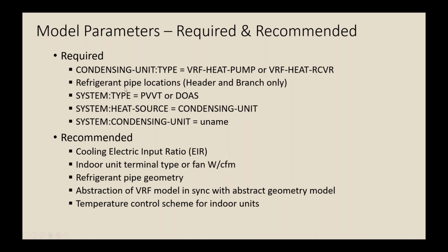You also have to specify the locations of refrigerant pipes, and I'll describe what these terms header and branch mean in terms of the program in a little bit. At the system level, you can only apply a VRF to either a packaged variable volume and temperature system, a PVVT system in DOE2, or a DOAS system type. So it's only applicable to those two system types. You have to know that and limit yourself to those system types.